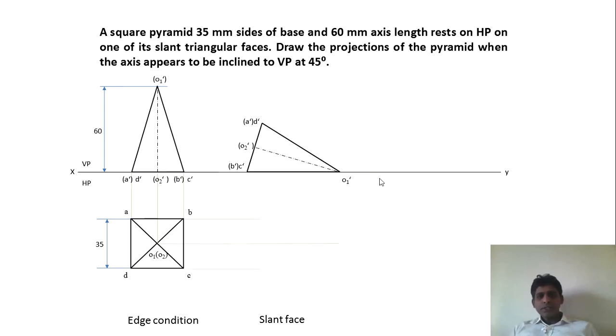Next, you draw the projections. Take all the horizontal projectors and the vertical projectors. Wherever they intersect, name the points. Here be careful. Point A from here and point A from here have intersected here. So this is point A, and likewise B, C and D. So name it accordingly and join the boundary lines. That is BA, AO1, O1D, DC and CB. So this forms the boundary.